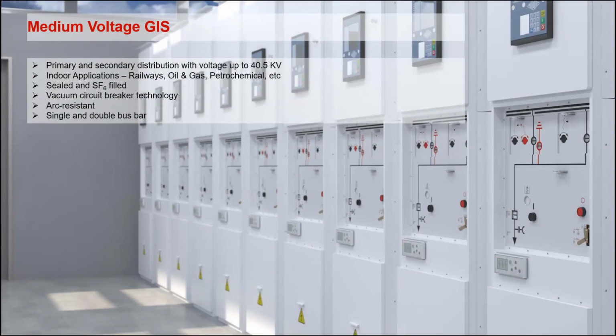So medium voltage GISs are used in primary and secondary distribution with voltage up to 40.5 kV and currents going up to 4,000 ampere in some cases, but usually it is around 3.15 kiloamperes continuous rated currents. And these are mainly for indoor applications such as railway, oil and gas, petrochemicals. And in these panels, the important thing is that the primary part is sealed off and filled with SF6, which gives it very low maintenance and high operating parameters.